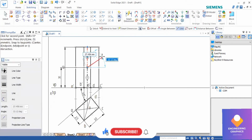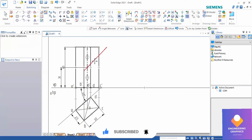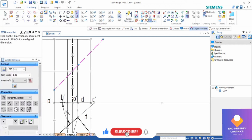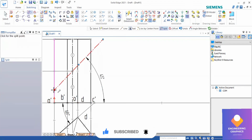Now I'm drawing an angle of 40 degrees, that is the section plane. For that I'll select an axis. Okay, using the extend to next command, I'm going to extend this line. Okay, so the upper portion of that cut part, I'm going to make it thin. The lower part we should make it a thick line. Okay, using the split command, I'm going to split it exactly where it has been cut. So it will be easy for us to create the thick and thin line difference.